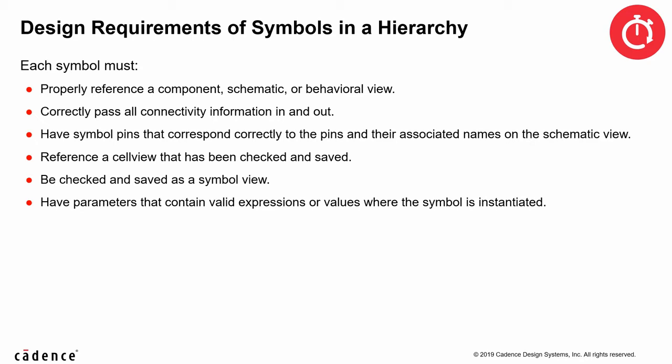It must reference a cell view that has been checked and saved, and these must be checked and saved as a separate symbol view. So in the library manager, for each cell you will see a schematic view and a corresponding symbol view. And each symbol must have parameters that contain valid expressions or values where the symbol is instantiated.